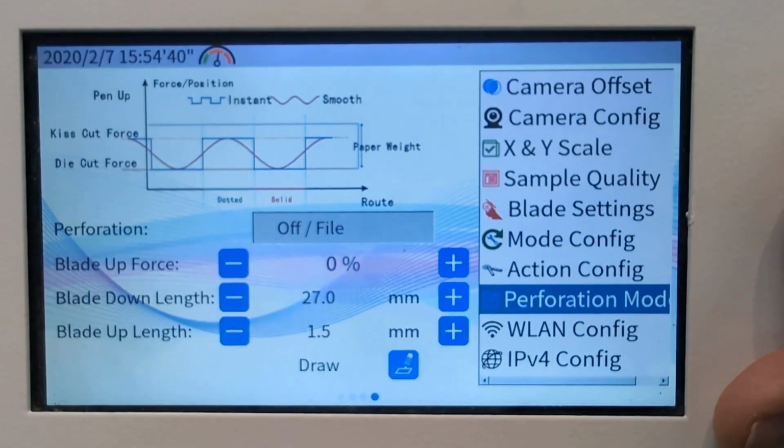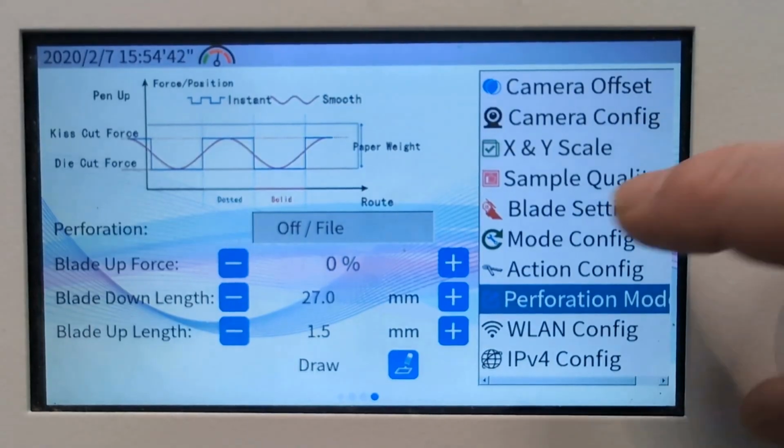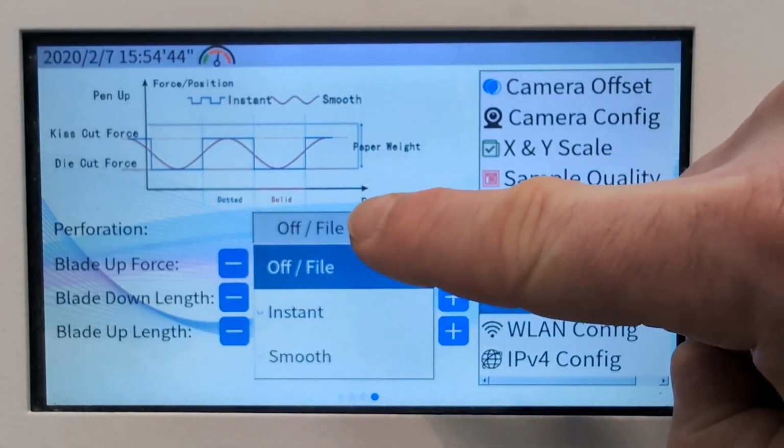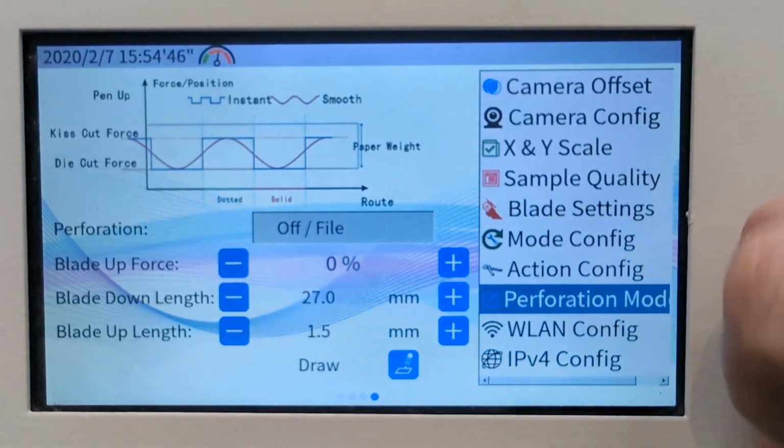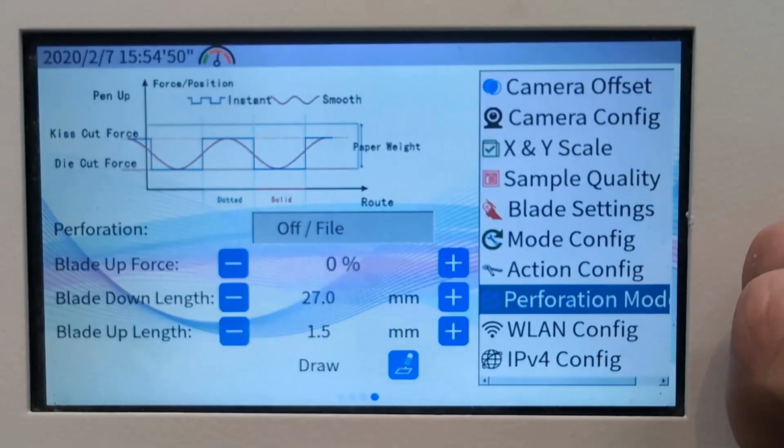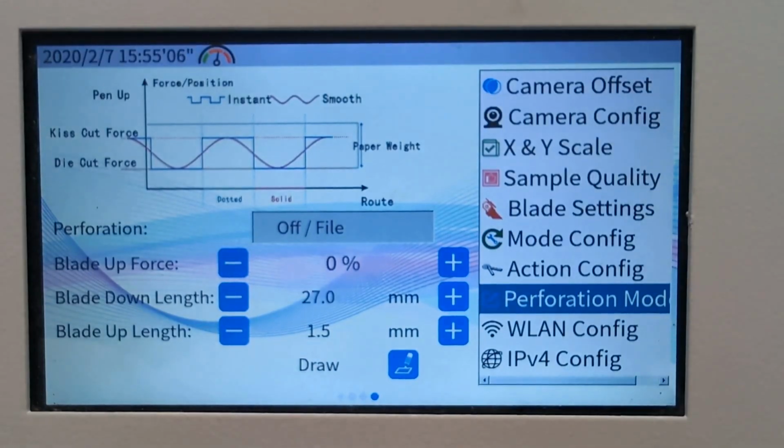So the cutter applies it at output instead of embedding those marks in the artwork, which gives us flexibility and avoids accidental printing. The perforation simply isn't being driven or controlled anywhere in the workflow except inside that specific PLT file, which is precisely why it's marked as File in the system configuration settings. The perforation mode is activated by what we control using the color Cyan within the plugin.